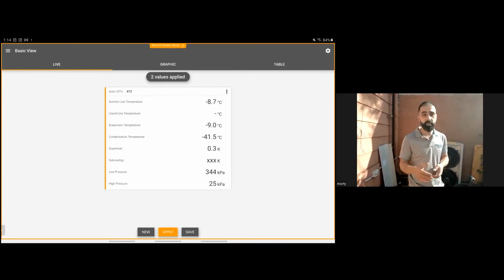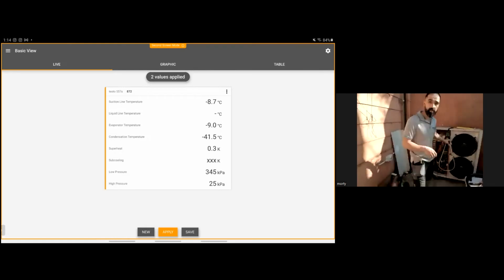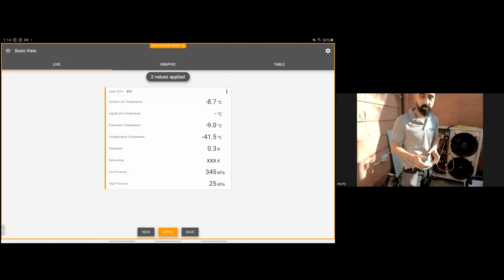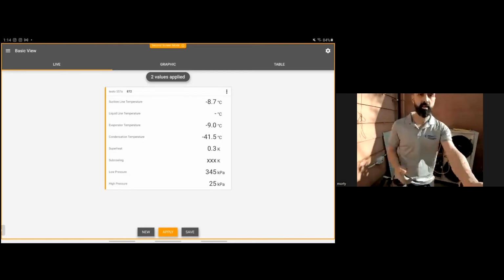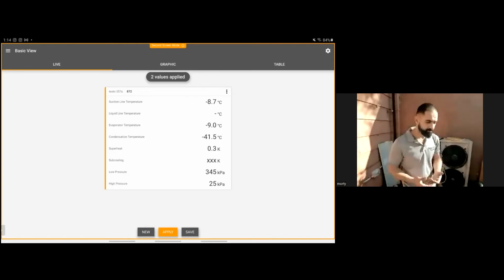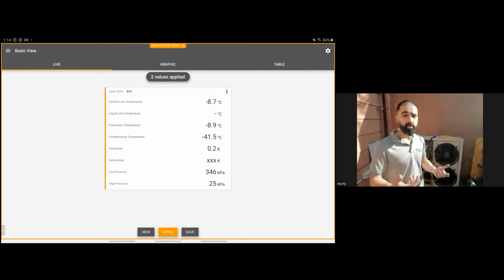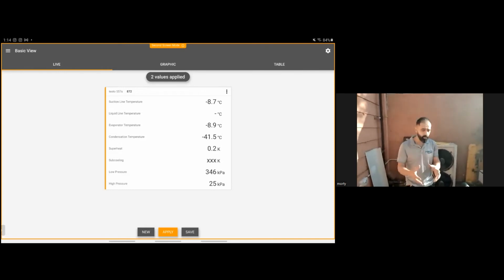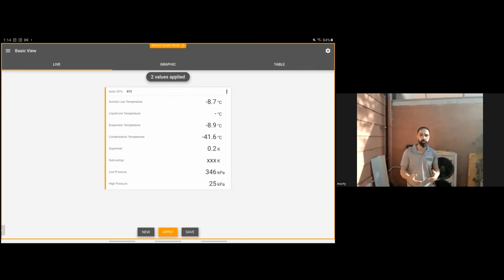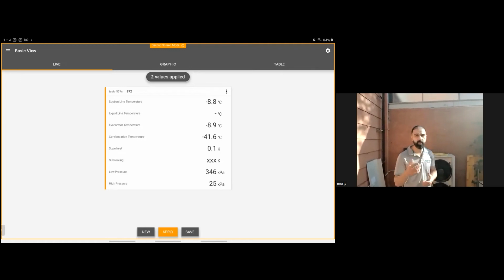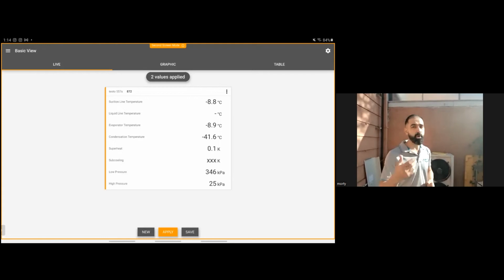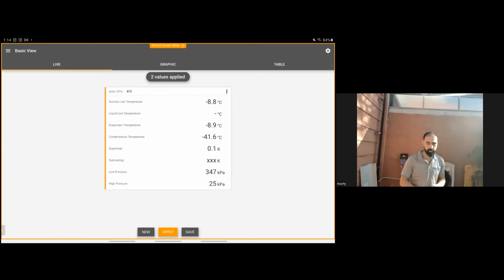Compressor on top, generally, I'm talking about a compressor in a can. I'm not talking about a semi-hermetic. Semi-hermetic, do not touch the head. They are slightly warmer on the head. The can compressor on the bottom, where the oil migrates, you don't want it too cold or colder than your suction, or sweating like your suction, because that is a sign of flood back. So you might need to go get your van and then double check everything.